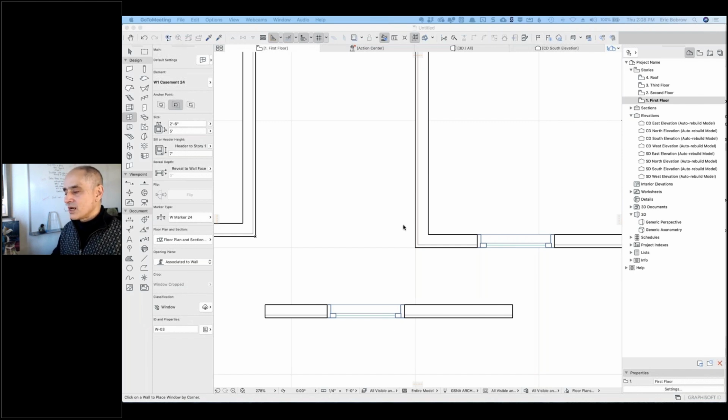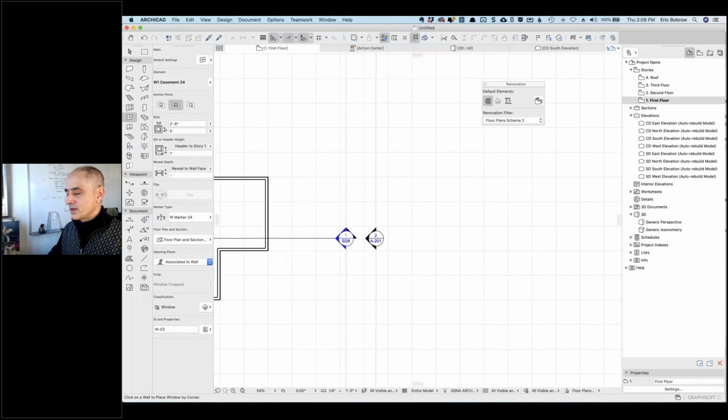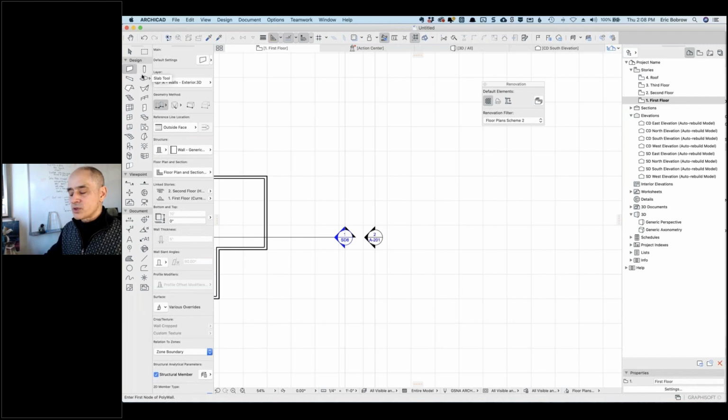All right, so let us say here I'm going to turn off the grid snap, and let's say that part of the building, I'll just move over to the side here, part of the building is on an angle. Now I'm just going to do it as an angled box, but of course it could just be one wall, one room, etc. So when we're doing a box of walls here, I can do a box that's going horizontally or on the axes, or I can say I'd like to do it on an angle, and then the first two click points are going to define the angle, and I can either type in an angle, or I'll just do it sort of arbitrarily, and then this gives me my other side.